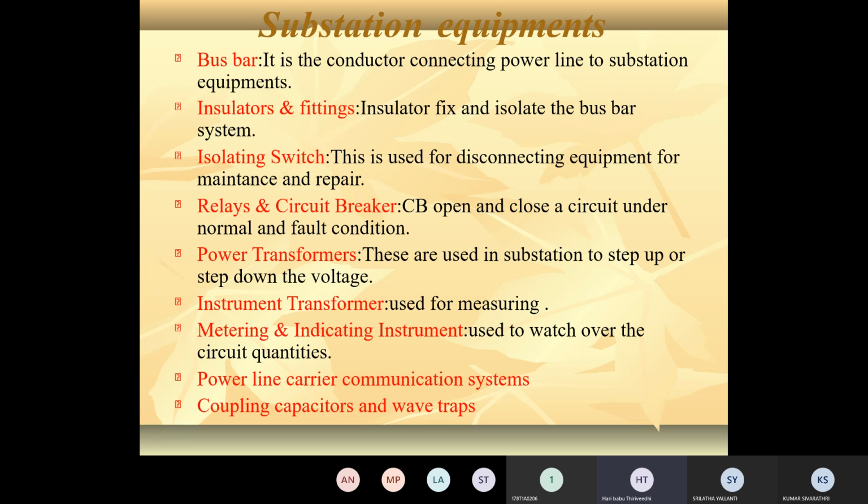Suspension insulators are the most used insulators, and they are used for voltages greater than 11 kV, up to 33 kV. Each disc in a suspension type insulator is rated at 11 kV. Strain insulators are used where junctions come into the picture, otherwise at railway crossings or road crossings.